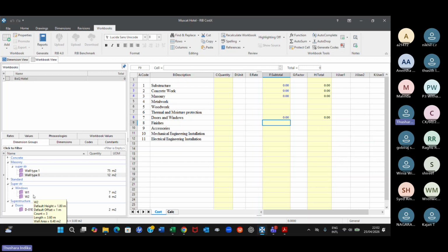So I'm not going to measure any finishes because it's a matter of creating dimension groups and then just measuring the areas. I have shown you how to measure the areas both in the substructure and also in the superstructure, when we measured the slab areas. You know how to measure the areas, like control, you can use the shift key and get the area. So it's easy. And then when you prepare the bill, you need to drag and drop appropriate quantities. That's all. Now I just wanted to show you something different.